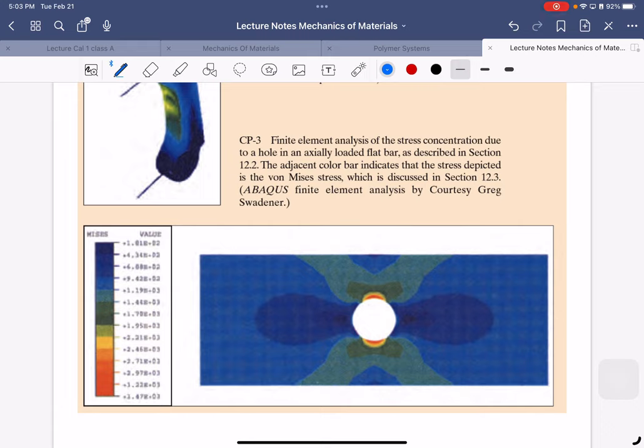If you give more stress, later it will break, right? It's the same thing. If you have a hole here, it means that if you give more and more stress, this hole will have some concentration of stress. Stress is going to increase, and eventually it will have a crack here.